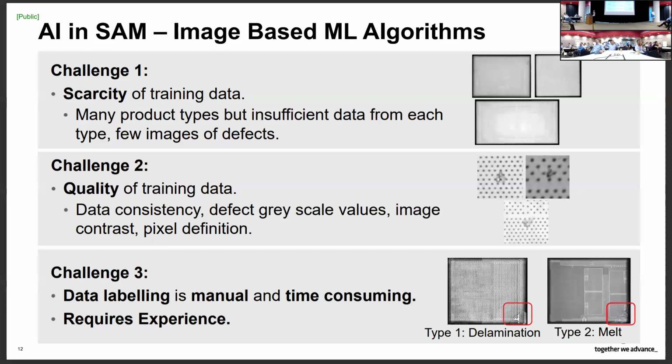So I think the problems that we talk about have already been said in the earlier talks in terms of scarcity of the data and defects. In general, by the time you reach high volume manufacturing, you're looking at defects in the ppm range. You won't go at the early part where you have many kinds of failures. So finding defective images is very tough. And if you do find them, they may be spread out over different reliability weak points or even in the few returns.